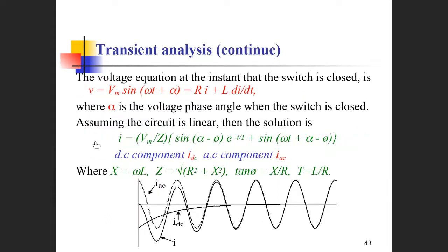Now, suppose the voltage we supply is a sine waveform with a phase angle alpha and an angular frequency omega. Because we are talking about transient analysis, we take into account the instantaneous values of voltage. So suppose we have the instantaneous voltage v, which has a max value V, a sine waveform and phase angle alpha. It is supplied to the impedance, as shown in the previous slide.